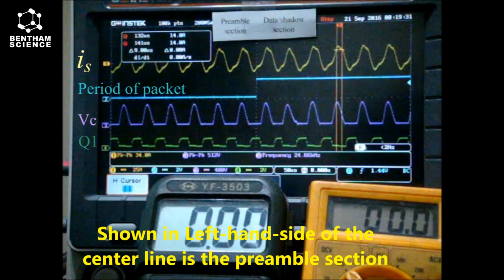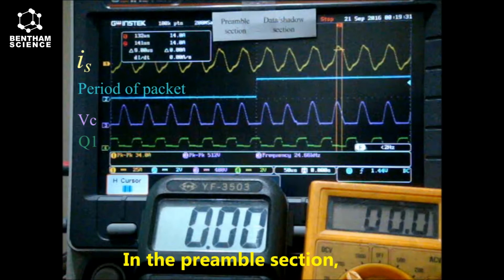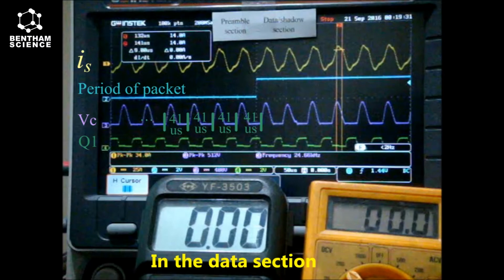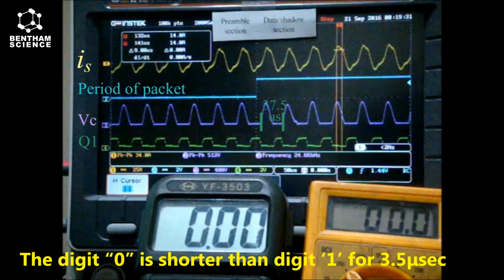Shown on the left-hand side of the center line is the preamble section, and the right-hand side is the data section. In the preamble section, there are data bits. Those are digit 1 without modulation. The time period is 41 microseconds. In the data section, there are digit 0 with modulation. The period is 37.5 microseconds. Digit 0 is shorter than digit 1 by 3.5 microseconds.